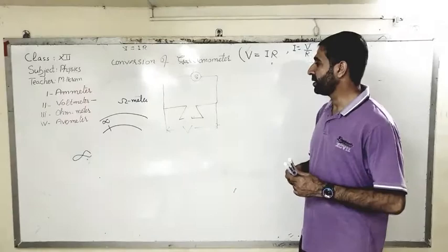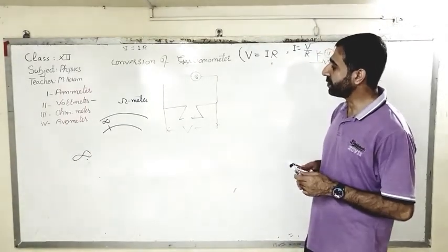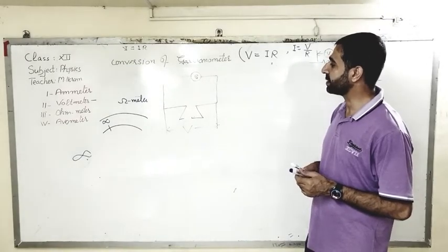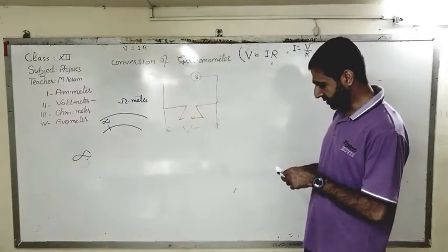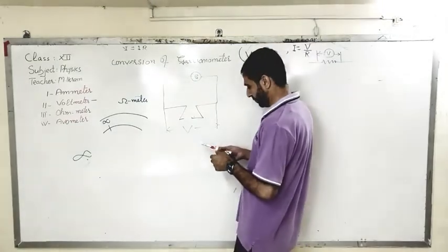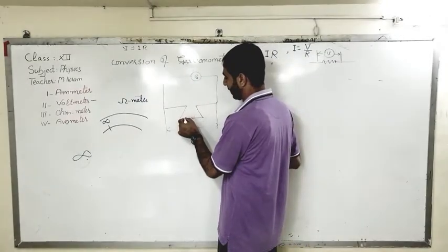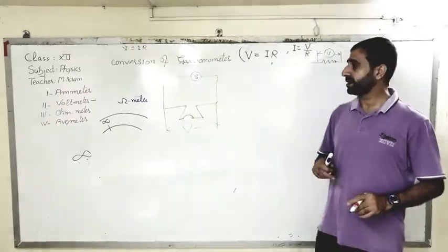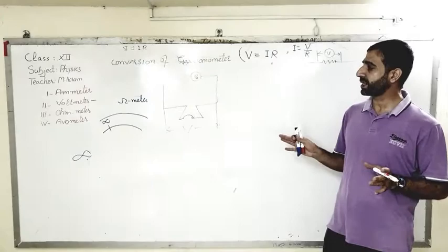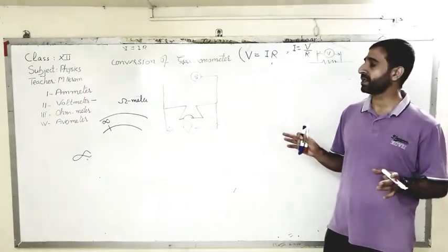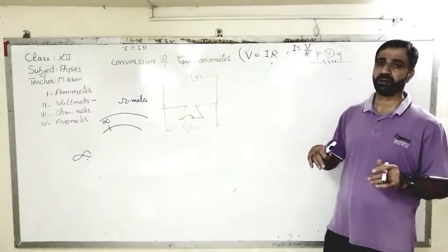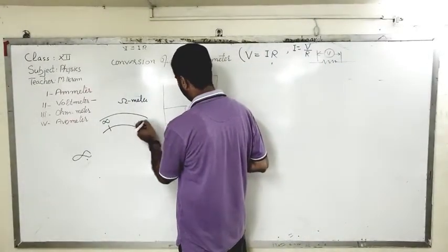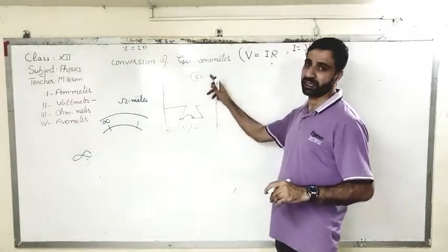Now look, then what we will do for the next one, that is the short circuit case. When we short circuit, like just directly connect, then there will be a conducting path and the resistance will be least, and the galvanometer needle will give you a full scale deflection, and we will note down that current.